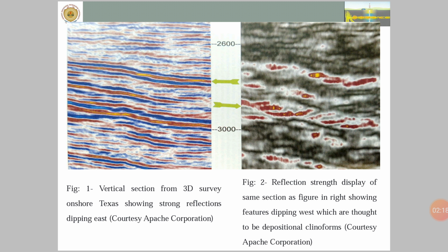The next thing which we require to understand is the source line spacing, and in this case we will find SLx is equal to 10 to the power 6 divided by Bx into Ns, where Ns is the shots per square kilometer and Bx is the bin size in the x direction. If it is a square bin, Bx is equal to By.